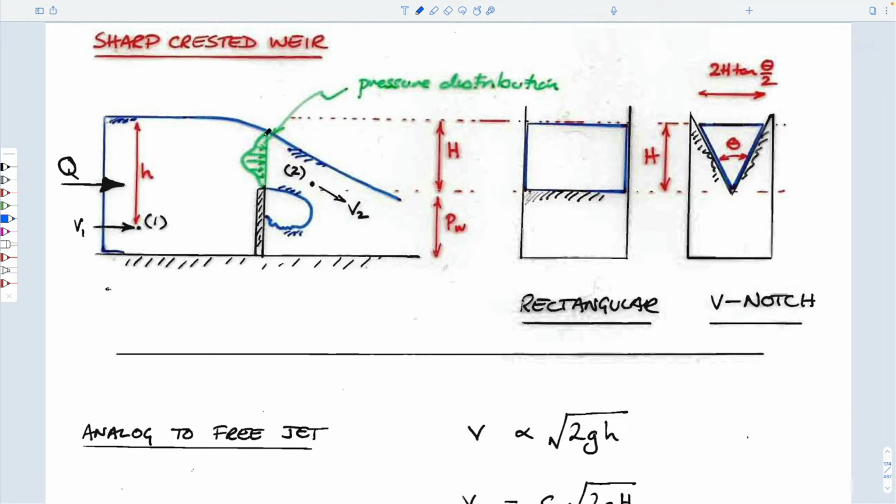And the velocity across here is not constant. So that's a wrinkle, I guess, on Bernoulli. We kind of need it to be constant. You also get this separation. And so you could imagine that if you thought that the top streamline was this streamline here, and the bottom streamline was this streamline here, which I guess if it was a very low creeping, very slow velocity creeping flow, that would be it, then you wouldn't have this portion opening up. The reality is that you get this separation, so-called separation, at this interface.